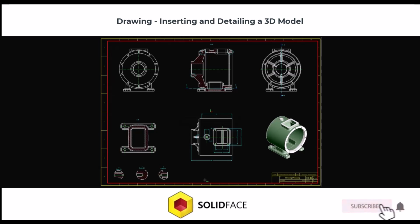The video explains the process of creating 3D models, drawings, and dimensions using a CAD tool. It details the steps for inserting 3D models into drawing files, creating section views, editing views, modifying dimensions with various configurations, and ensuring associativity between 3D models and drawings for accurate updates. The final steps involve setting up sheets in the paperspace module and printing the final drawing at the paperspace default scale of 1.